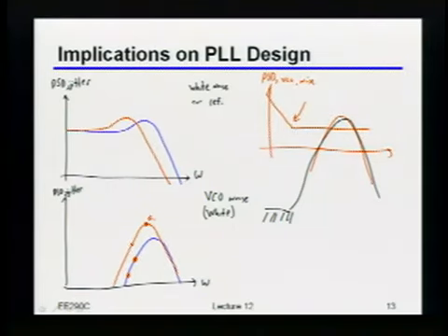So what is that? That's not the origin, right? What's not the origin? The PSD where you've drawn it. Well, okay, I mean, yeah, this does technically go off to infinity, right? Oh, no, I'm saying the x-axis. Isn't it from the oscillation frequency? No, so what I'm drawing here is the spectral density of the equivalent voltage noise going into the oscillator. Right, that's not zero, right?